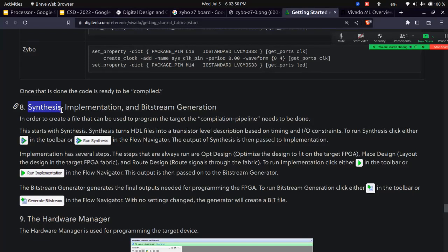When you synthesize and simulate again, all the simulations happen on the synthesized design, and the output is not the same. That means your design is not synthesizable. That's what you have to learn. Whatever design you put may be only simulatable, not synthesizable, so you have to make a design that is synthesizable. It took us 2 days to realize that the code was not synthesizable, and then we made a few changes.